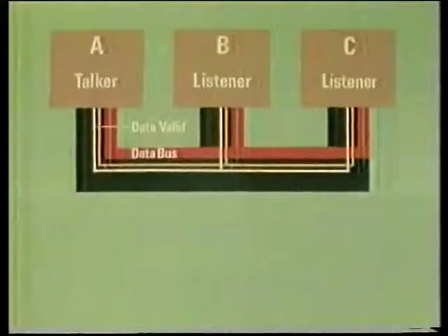For consistency, the standard insists that all signals should be ground true. That is, low for true and high for false. All this means is that the ready for data line has to be called not ready for data. It still goes high and low in exactly the same way as before, and it still means that the listener is ready when the line is high and not ready when the line is low. So with that in mind, let's see how the 2-wire handshake fares with 2 listeners.